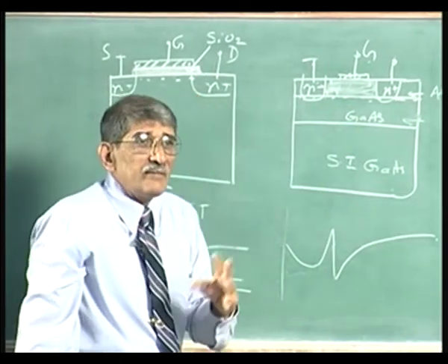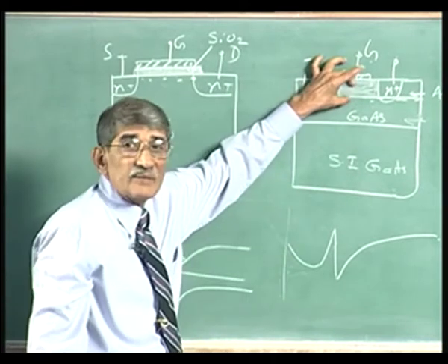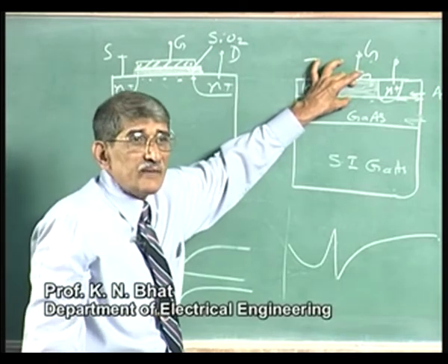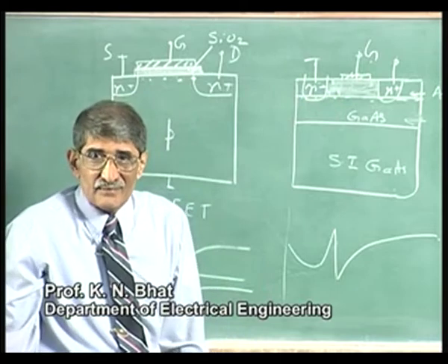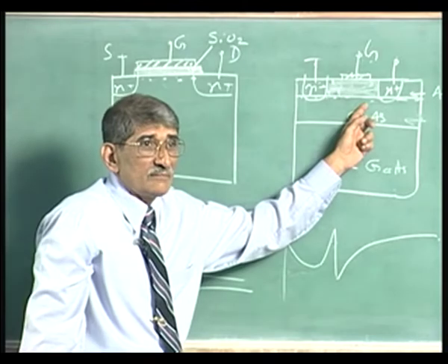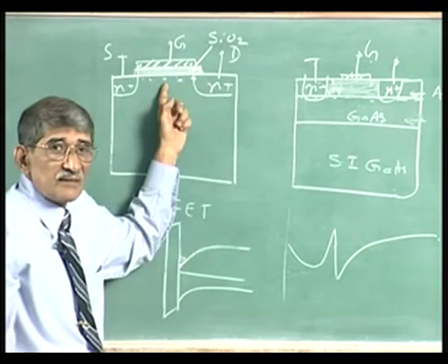All that you will have is the MOSFET equation with C oxide replaced by the Cs, and threshold voltage replaced by the threshold voltage of this device, which we call the off voltage. Mobility is replaced by the mobility of this 2-dimensional electron gas, which will be tremendously large compared to that.